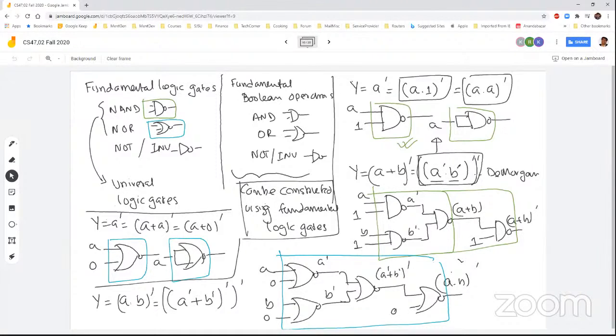You see that there is this concept of timing, right? Every synchronous circuit operates with respect to the clocks, and that means the timing sense and delays are very important to tightly control throughout the logic circuit at the electronic level. Now, let's say you are building a logic circuit which logically sounds very good, but some of the gates, like the NOR gate you get from the vendor, are slow.